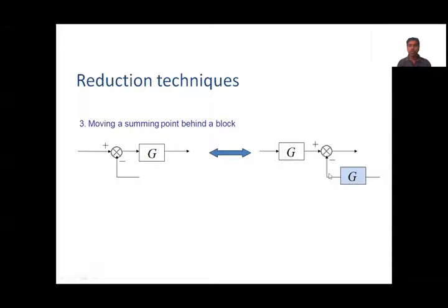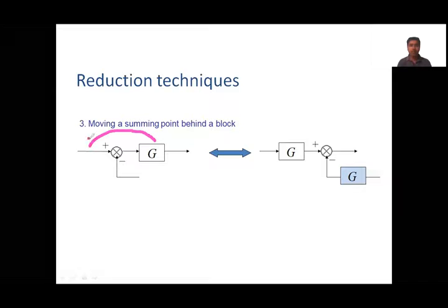The ultimate point we have to remember is that after the simplification, the overall gain should not be different; both should be the same. In such a way we can alter the blocks in any manner for our simplification purpose. So G is changed from after to before.